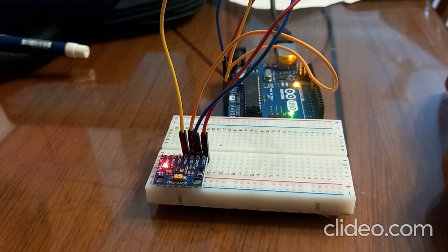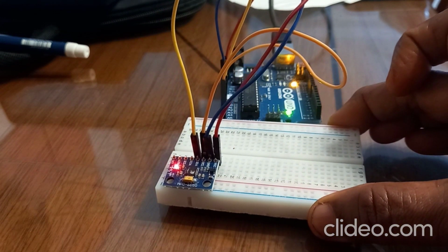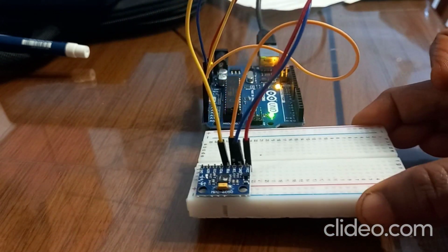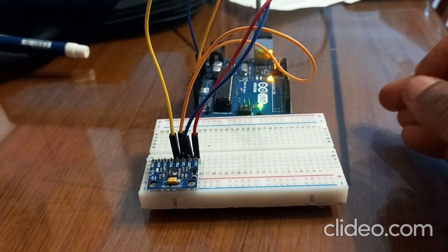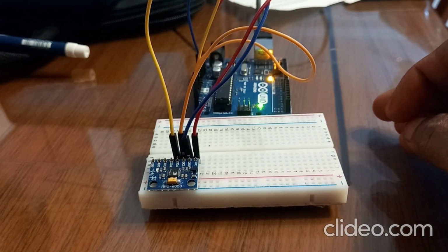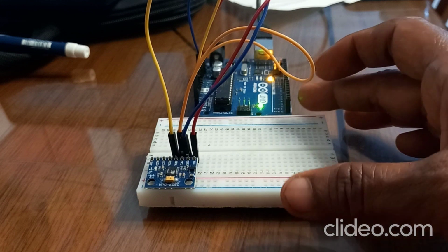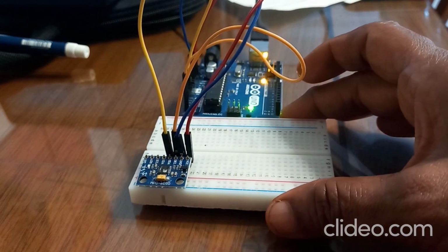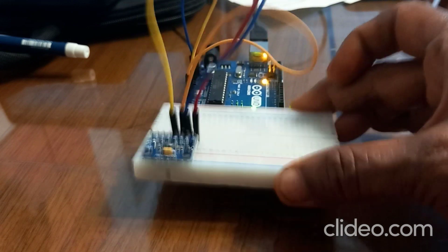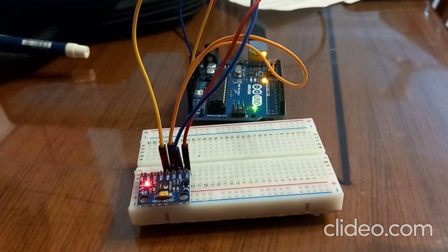And you can detect the movement or sudden acceleration if the object is moving very fast or sudden fall. That also you can detect with the help of this accelerometer. And you can monitor the vibrations in the machine. If you attach this to some machine, if the machine is vibrating, you can get the change in values in x and y direction. That also you can monitor. You can monitor the vibrations in the machine or on the surfaces.